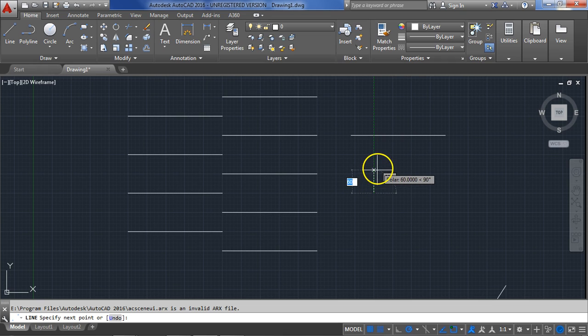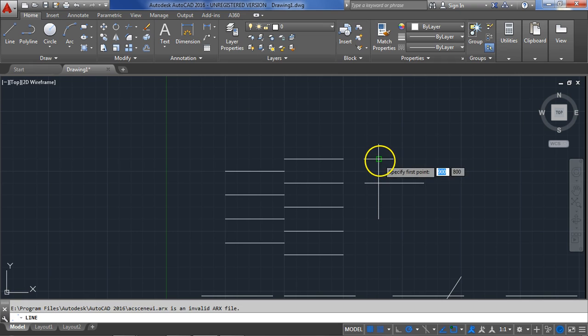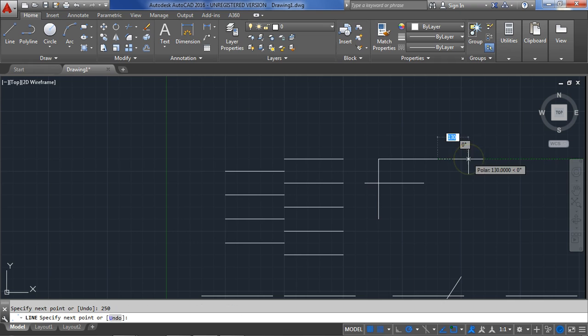The nice thing, when these things are on, is that all you have to do is start typing the distance, if you know how much it is. Go down. And now I have made a box. Spacebar, when you click it, will automatically restart an old command, or it will end a current command, just so you know.